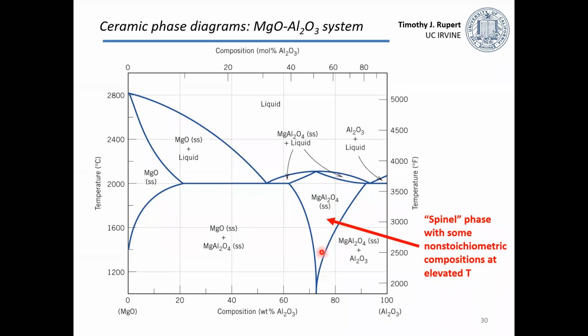And it's like that intermetallic, but it's also worth pointing out that although at low temperatures, it has a perfect stoichiometric compound formula of 1 magnesium, 2 aluminum, and 4 oxygen. At high temperature, because these are higher temperature materials, you can get some solubility. It means there can be some variation in that magnesium and aluminum relative amount. But again, you can work your way into different regions of this phase diagram in the same manner.